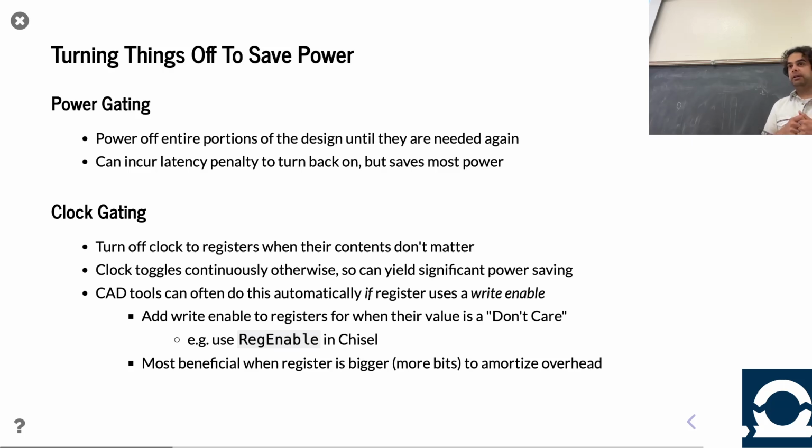There's a way to write that in Chisel. So it's not the same as the X in Verilog, because the X in Verilog, great question. So the question was, how do you indicate don't care in Chisel? The X in Verilog is kind of annoying because it both indicates, as a designer, I don't care what the value of something is, as well as, in hardware, due to the nature of simulation, somehow there's a value it can't determine.